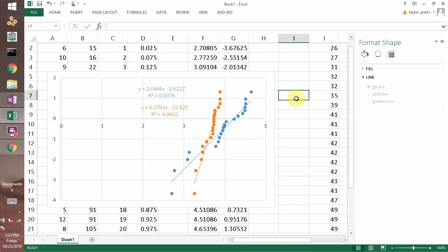So if you were to extrapolate out to now 1 million samples, at least qualitatively speaking so far, it looks like the blue might keep on going down to fail at a really low stress or a really low elongation, whereas orange might not extrapolate out as far. So this all depends on extrapolation, going beyond your data set. That's always a dangerous thing to do because you don't know what it's actually going to do, but it's better than not doing anything, using your gut feeling, which is what we do anyways, right?